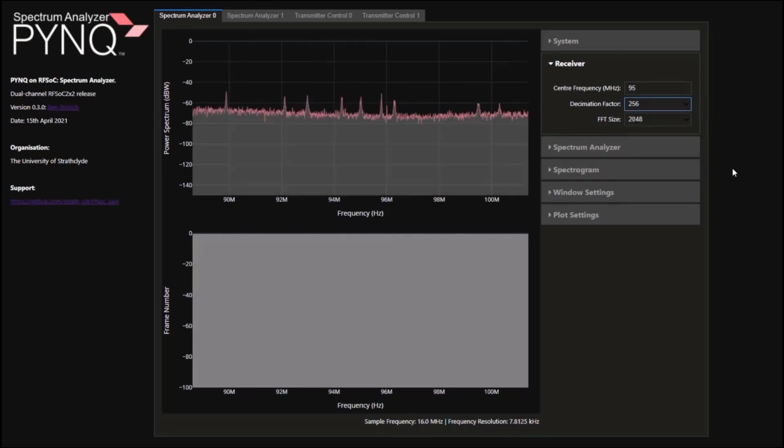By decimating further, each of the individual peaks become easier to identify. From the spectrum plot, BBC Radio 2 is shown at 89.5 MHz. BBC Radio 3 can be identified at 92.1 MHz, and BBC Radio 1 is shown at 99.5 MHz. There are various other peaks in the plot, but we won't go through any more of those today.